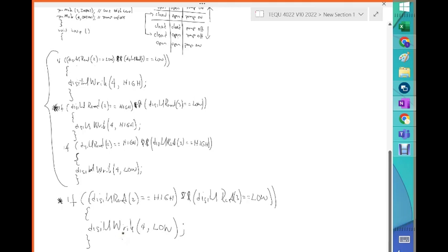Okay? There's something that needs to be done here to understand why our code will fail. Although it makes sense when we write it down, during execution both of them will fight each other. One will turn the pump high, and the other will very quickly, a few microseconds later, turn it off. The pump is not that fast, so it probably might stay off. But that's not a good design at all. Not good.